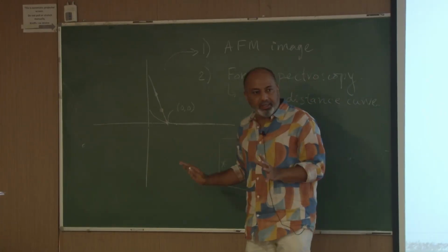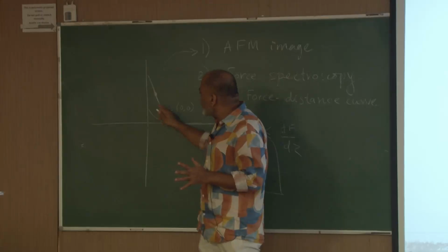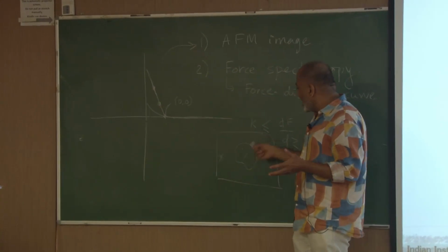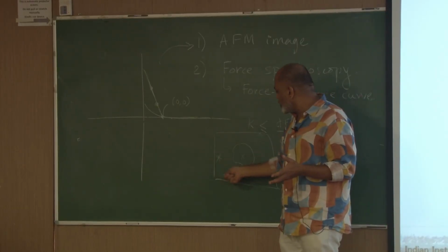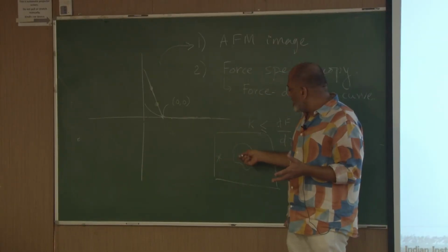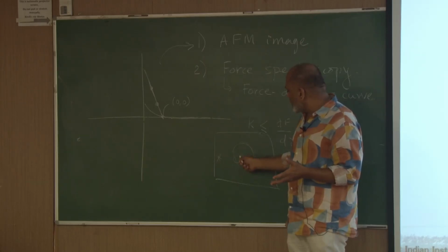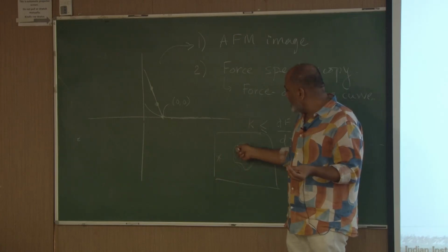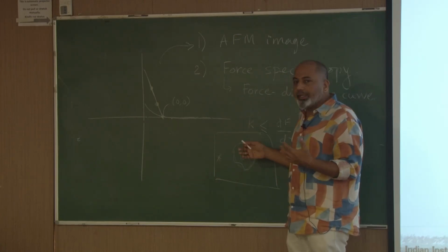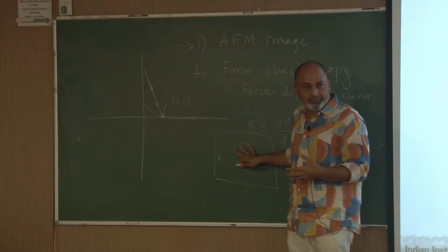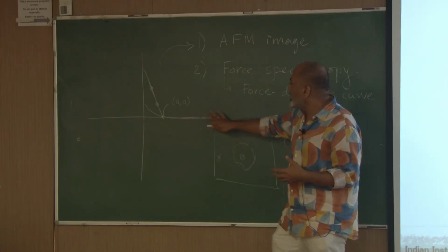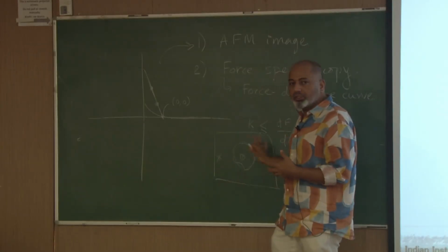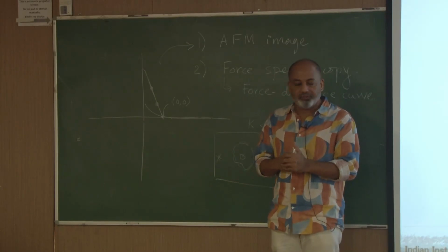So, that is about contact. You can use contact mechanics to determine nanomechanical properties. You can make a whole map. I can take one force curve there, one here, throughout the whole thing, and say, okay, this cell is like this, with a nucleus inside which is also of different stiffness. Locally the stiffness can vary, I press all over the place. I can get a nanomechanical map of this whole thing. So, that's one thing that you can do with force spectroscopy, measuring the mechanics while you are pushing on the surface.